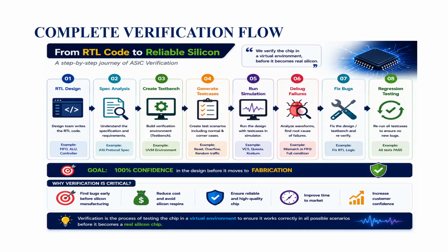Okay, after every test case has passed in the regression, we have to go to the coverage. As a verification engineer, we conclude that this particular RTL verification has been completed by using coverage closure. Coverage is a tool metric where we can analyze how much of the code has been verified properly.